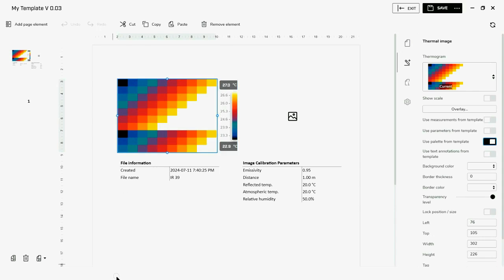This is where we now create the synergy between the camera capability and the template. Let's make the assumption that we are going to analyze temperatures between the max temperature of an area and a spot temperature. We're going to maybe subtract the spot temperature from the max temperature of the area. Our template needs to have that initially in the image so that we can then manipulate that information.